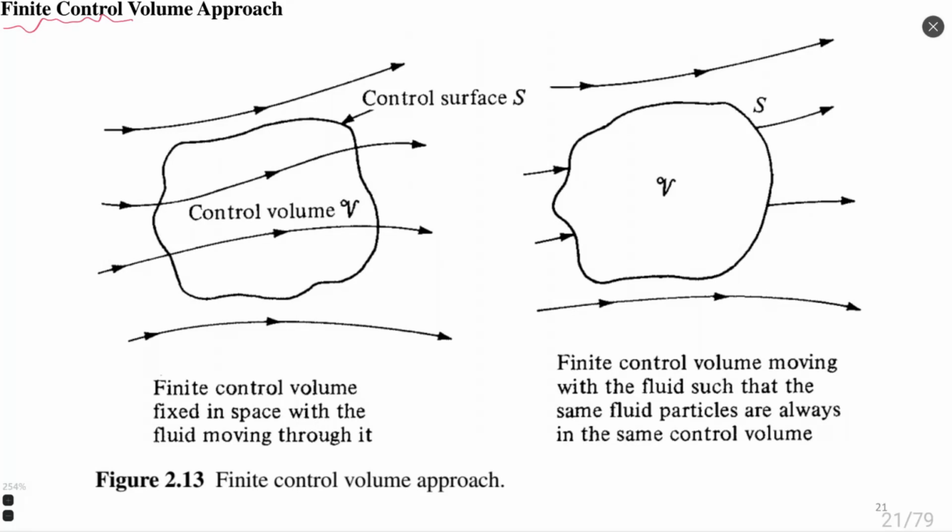The result of calculation for the Eulerian and Lagrangian approaches in general is the same. It's just a question of where the observer is. The observer stays outside of the control volume and calculates quantities of mass that enter and exit this control volume, or the observer is inside the control volume and is calculating the deformation of this control volume and its movement in space. In general, if we create a correct equation system, both of these approaches give us the same result.